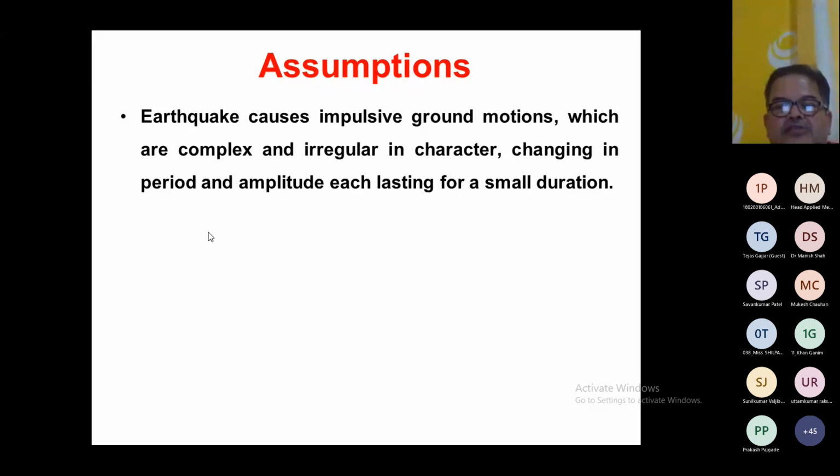So the code denies resonance, except for one earthquake: the Mexico City earthquake of 1985. It was a very low frequency earthquake, taking place 300 kilometers away from Mexico City. During this earthquake a lot of damage and casualties were observed, and everyone was surprised.